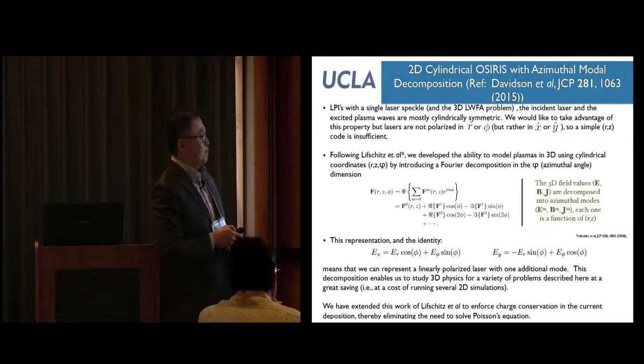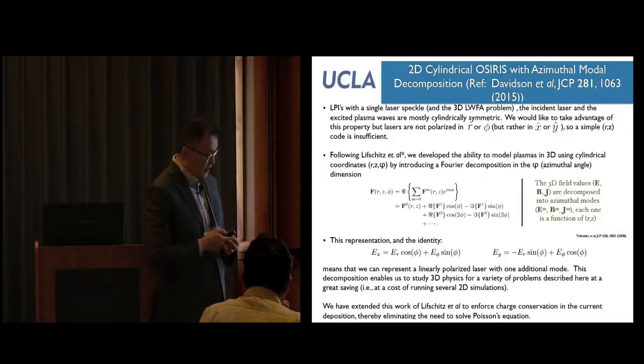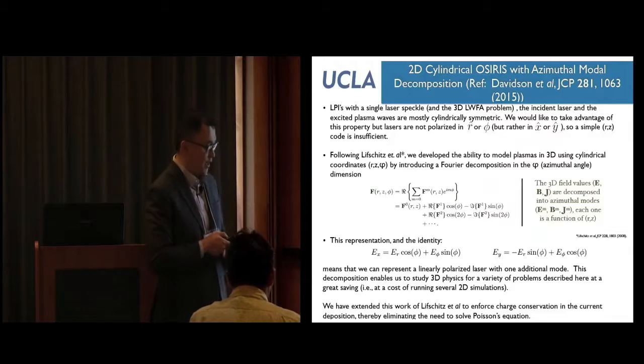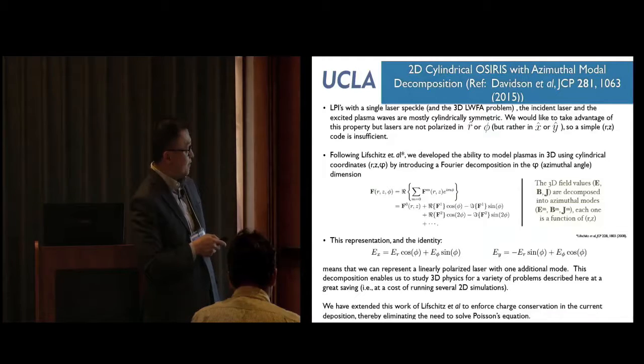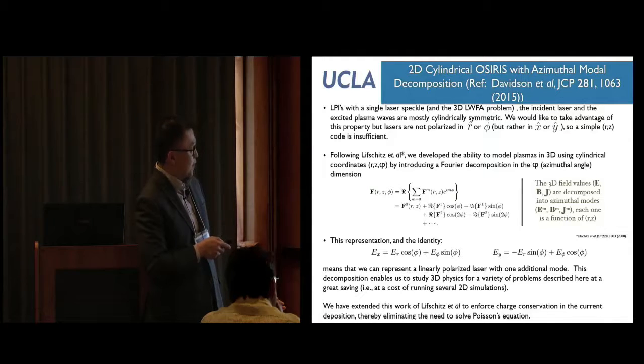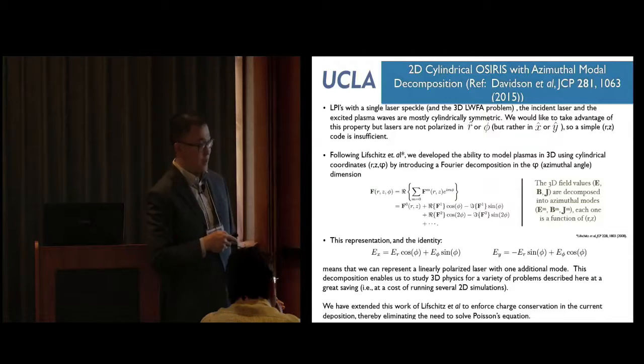So you can imagine simulating these with a cylindrical model, but of course that's not possible because the laser light is not polarized in the R direction or the phi direction, the azimuthal angle direction, but is usually polarized in X or Y. So you cannot use a simple RZ model to model the laser.